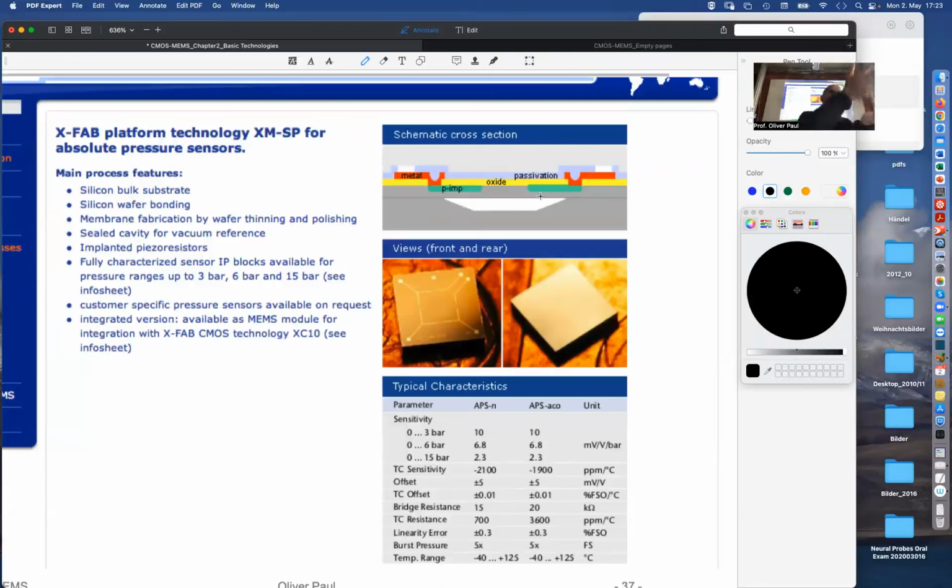So they produce a silicon wafer by some wafer bonding process and back etch process, by preparing a wafer with this kind of cavity and then bonding a second wafer on top, back etching that wafer to the final thickness of the silicon membrane thickness, and then doing a CMOS process on top of that front surface that looks as silicon to the CMOS technology, but it has these buried cavities underneath.